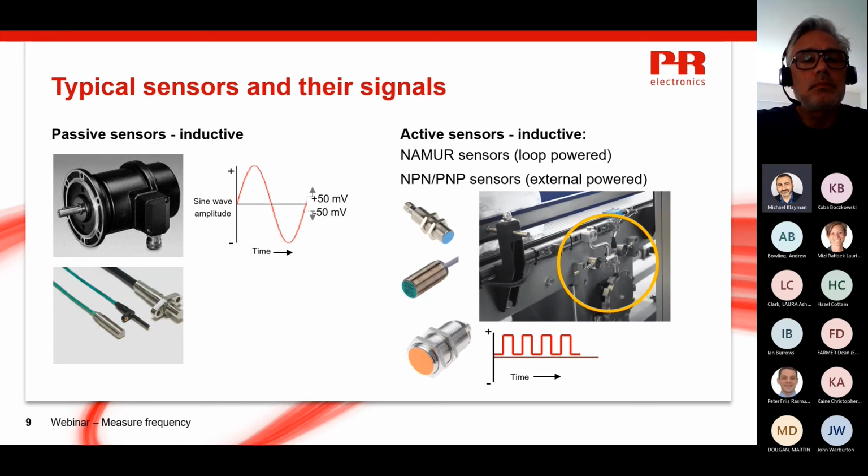Below, on the left side, is an image showing a few types of inductive pickup sensors, typically with a permanent magnet built in. They will detect a change in the magnetic field when the iron mass passes in front of them and generates a corresponding signal. The passive sensors are often used where powered electronic sensors are not able to be used. For example, high frequency applications and extreme temperatures.